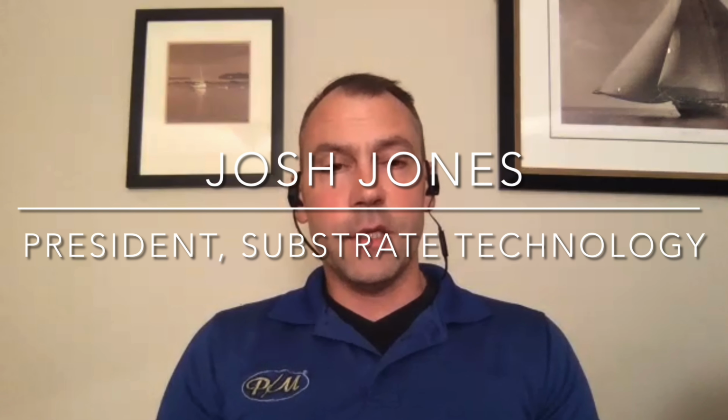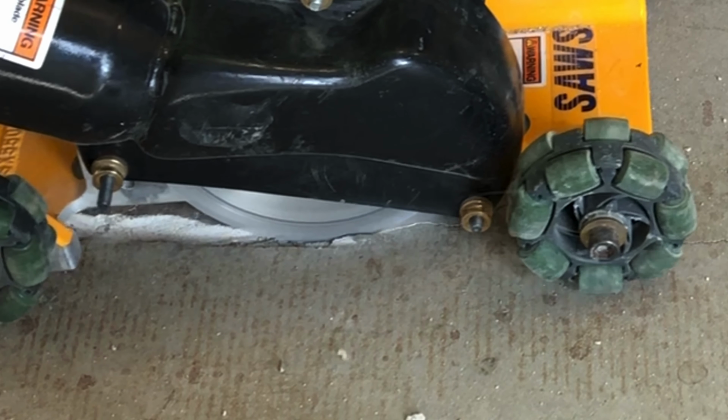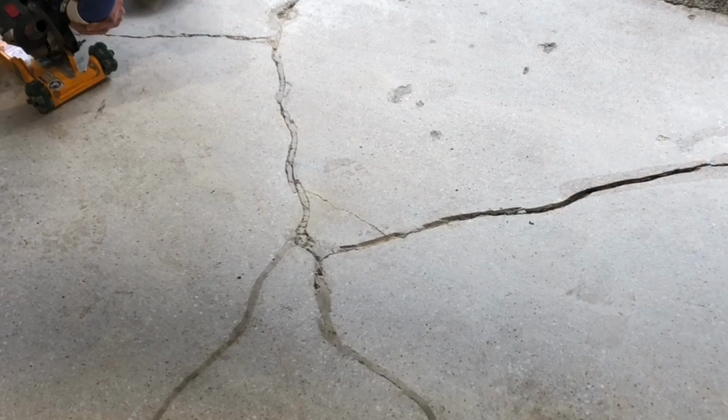Cracks can take place because of shrinkage after placement of the concrete slab. Basically, it indicates any kind of movement in a structurally rigid slab. So if there's any kind of movement, what the cracks are indicating is that movement was great enough to break that rigid material apart. Again, it could be during the placement, after it's placed, and the shrinkage that takes place could actually pull it apart to some extent. Or there could be movement after the slab was installed, whether it's because the sub base had moved. Nobody really knows, but it just indicates that there was movement in that slab that it just couldn't handle without cracking or breaking apart at that point.